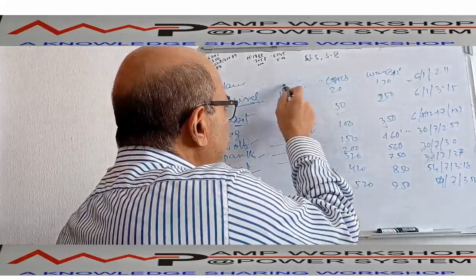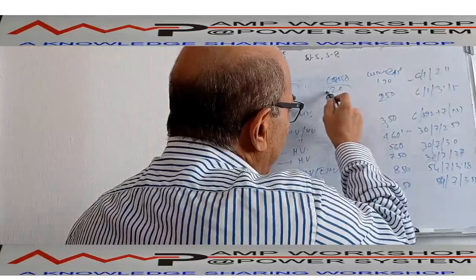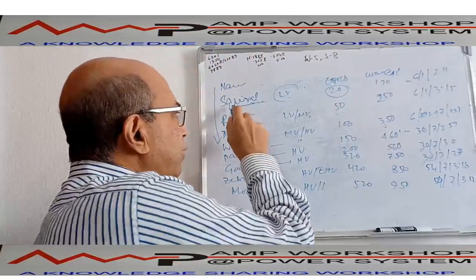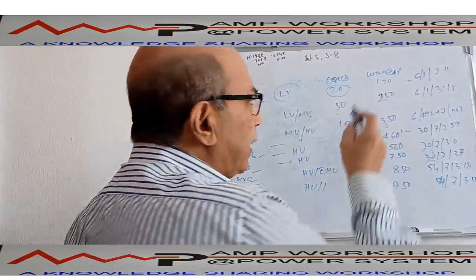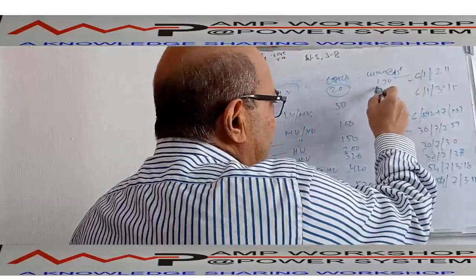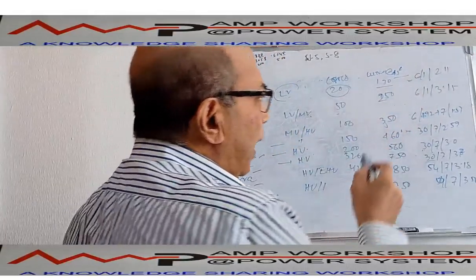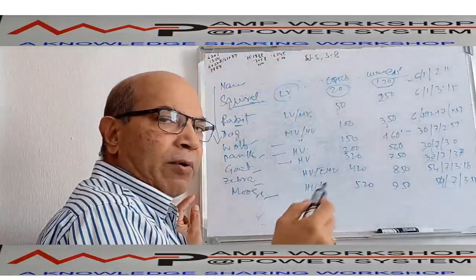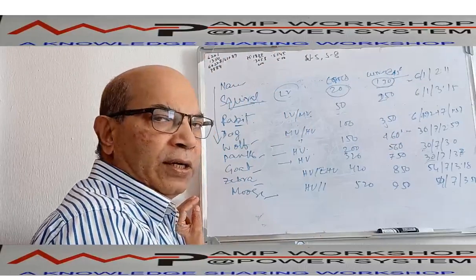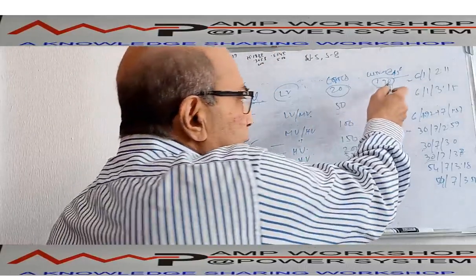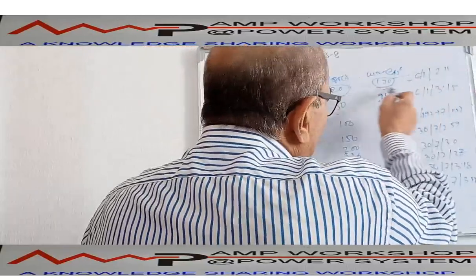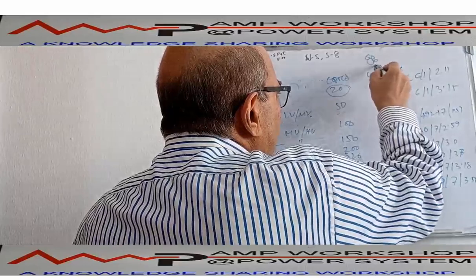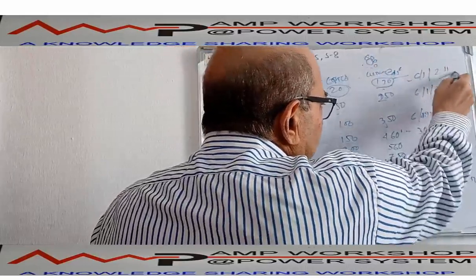In low voltage we use LV, where the cross section area of this squirrel conductor is 20 square millimeter, and it can carry current at 45 degrees centigrade temperature up to 130 ampere. Okay, 130 ampere means approximately 80 kVA power. It can carry approximately 80 kVA power. This conductor has one center conductor and a second layer of 6 conductors. All conductor diameters are 2.11.